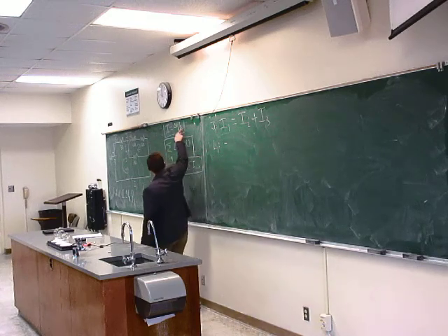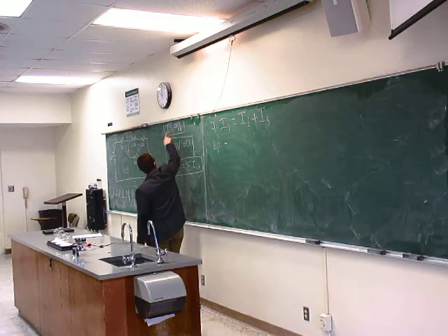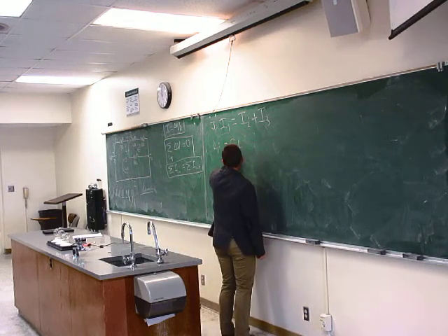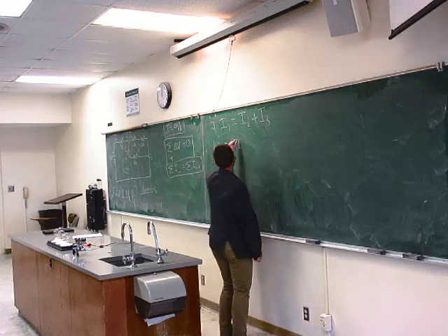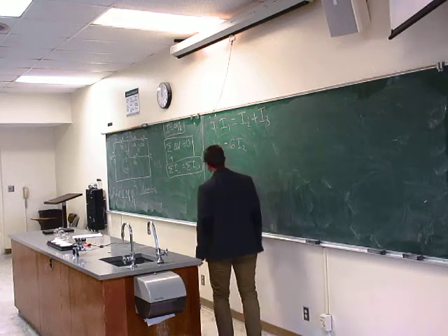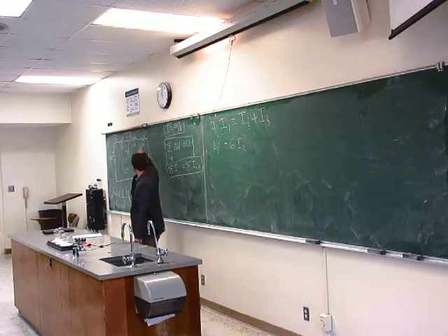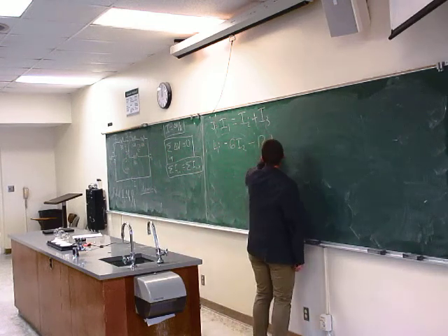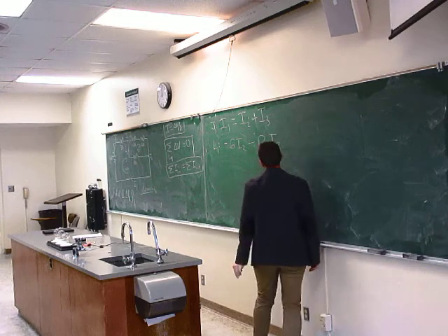If I multiply R to both sides, delta V would be negative R times I. So it would be negative 6 I2. And then after I cross the 12 ohm resistor, it's negative 12 I2.